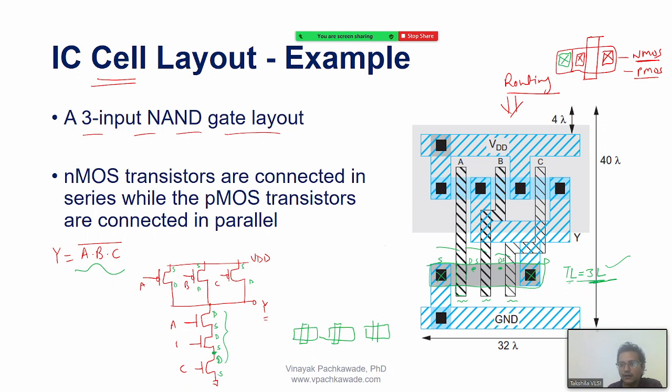So when you want to actually make such a transistor, the tool will help you. You have to define W and L for each transistor you take from the library.